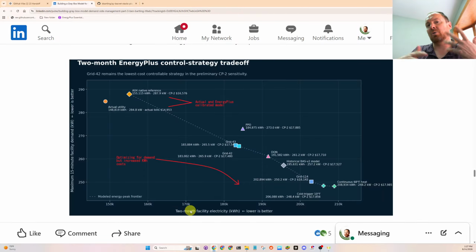The coldest Monday morning, which we were kind of optimizing for, is when they peak their demand. A really cold building starts up and requires an enormous amount of electrical energy to heat it up. So they peak on the coldest day in the morning, which is kind of opposite of peaking in air conditioning at the hottest point in the afternoon in the summer.